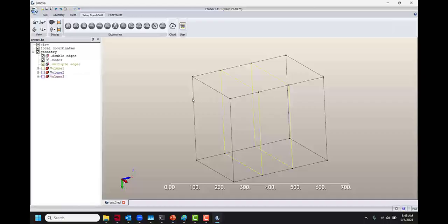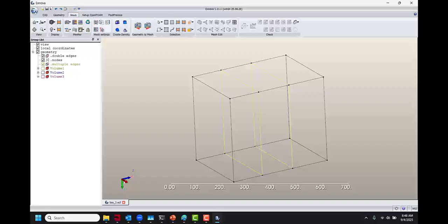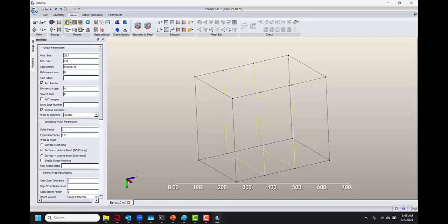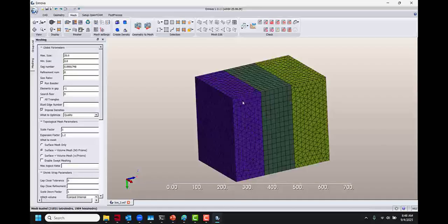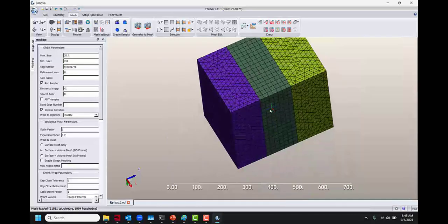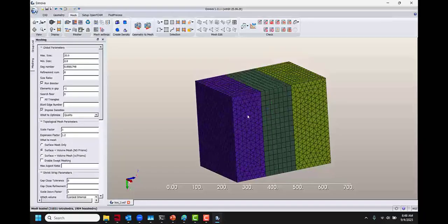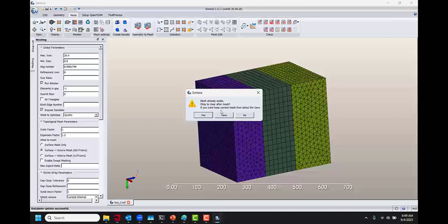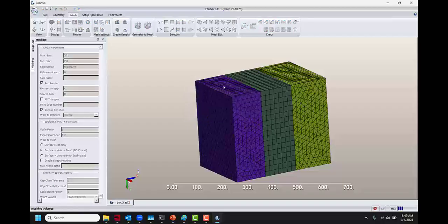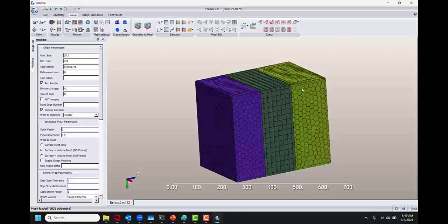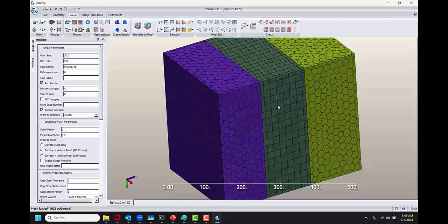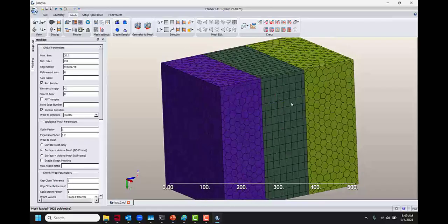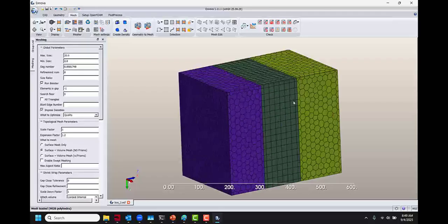And so now if we come back to the meshing tree and we make that, we get the swept mesh. And notice we've gone back to the tet mesher because I didn't press the polyhedral mesh. If I'd done the polyhedral mesh here and then meshed, and so now we have the polyhedral mesh everywhere. We have a nice swept mesh for our cell zones, all set to run on OpenFOAM.